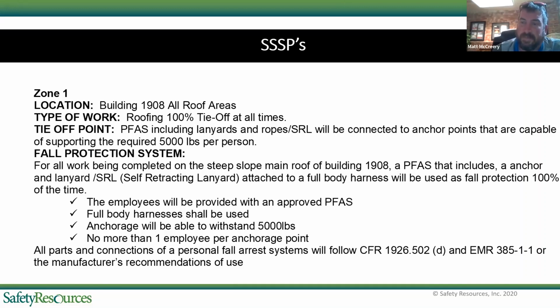So we have it about 15 pages long, but a lot of that's cookie cutter, and our competent people know that, but we have them focus on the emergency plan, the fall protection zones, which is what you're seeing here, and the JHA for this particular job.